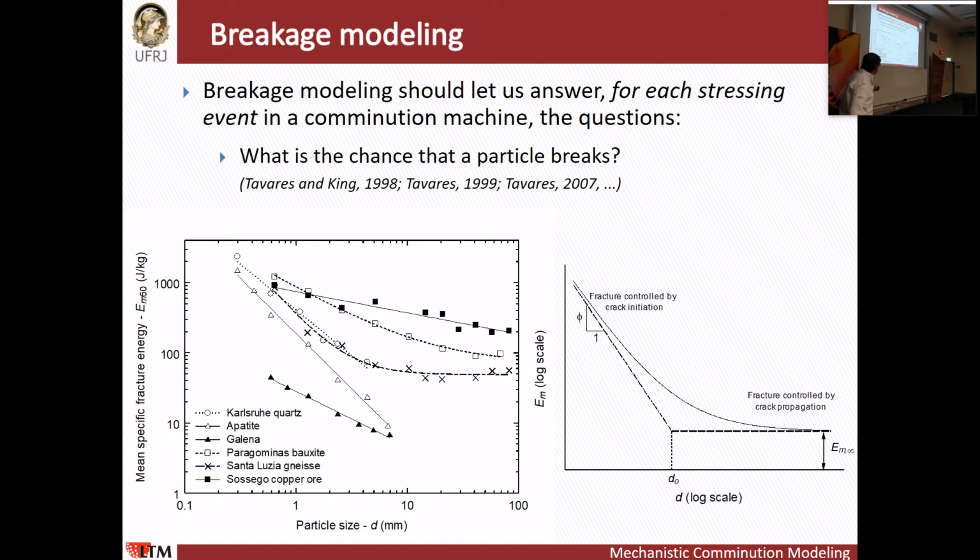Besides being able to explain this, the most important thing is to be able to characterize. By looking at this, you'll see interesting things that we know from practice, which is that some materials are very hard to crush, but actually become not so hard to grind. We know that. Sometimes it's a good, sometimes a bad surprise. On the other hand, some materials are pretty straightforward to crush, with very low energy required, but as you go to fine grinding, it really gets tough. That's the reason why industry puts a lot of money into testing, but we should be able to explain and characterize that independently.